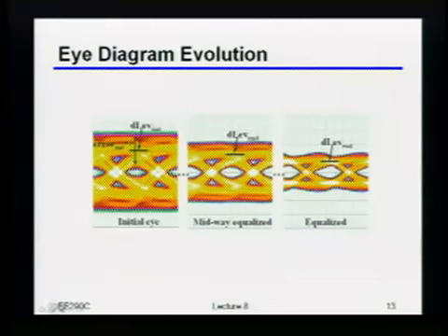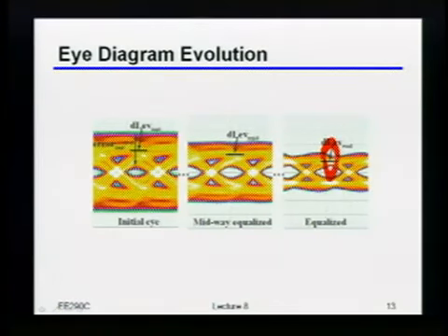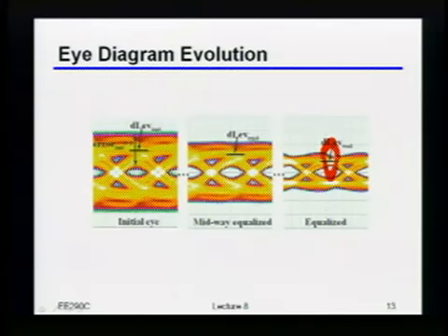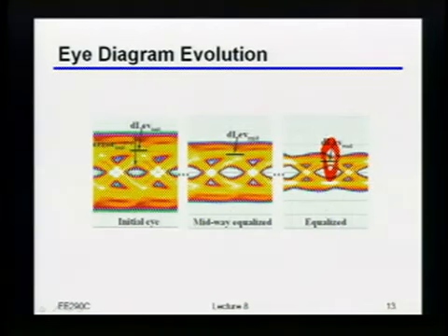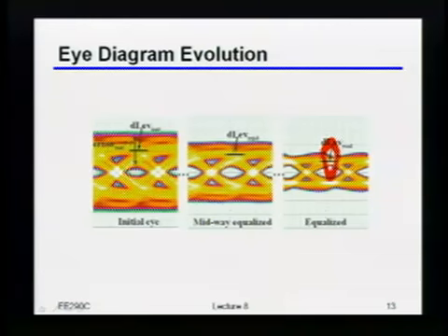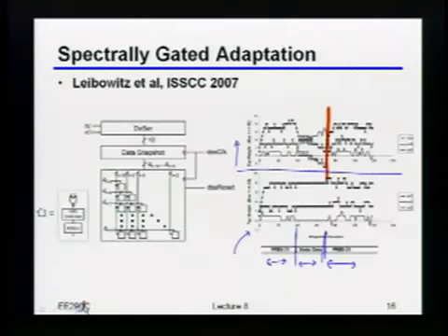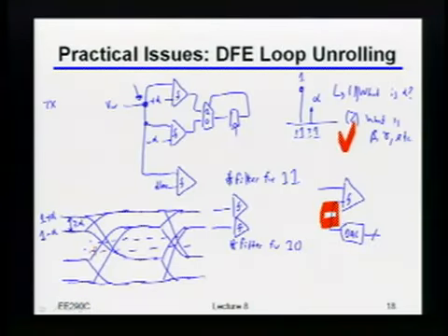we were taking this analog eye diagram, right? And so if there was some residual error around that level, you'd see it as the data level comparator saying, on average, oh, there's something above me, there's something above me, there's something below me, or something like that, right? Notice here, if I shifted this alpha level around, let's say, instead of over here, I actually put it there, the data level comparator doesn't know squat, right? Because that doesn't move the error around the data level. That just means that you're more likely to make a mistake on the data. Do you see what I'm saying?